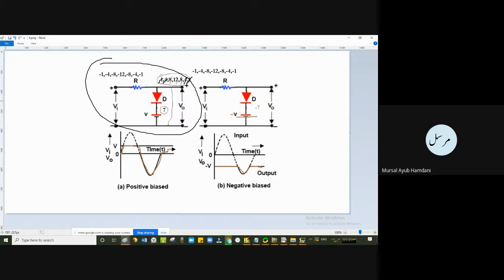And the reverse bias here is only possible when voltage at the positive side is less than voltage at the negative side. Since voltage at the negative side is always sitting at 7, for those values of the input less than 7, like 1, 4, 5, 6, we'll have the input going to the output, making it reverse biased. So here you can clearly see it's like that.